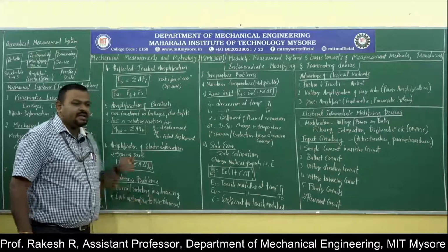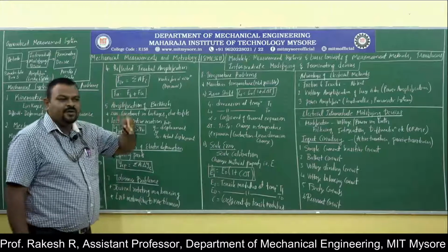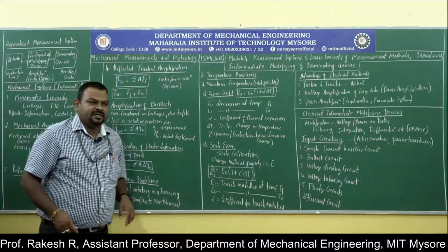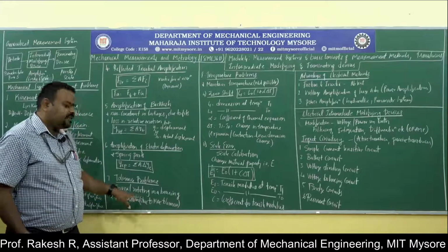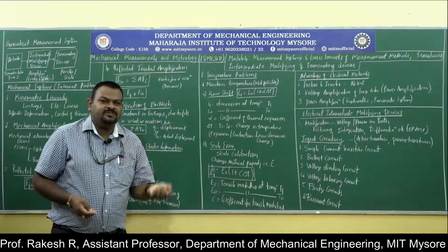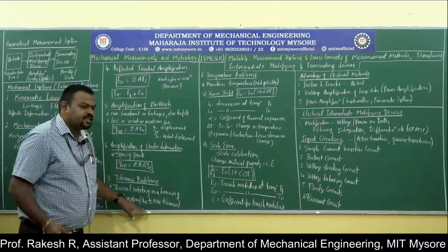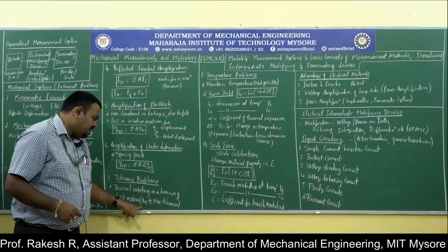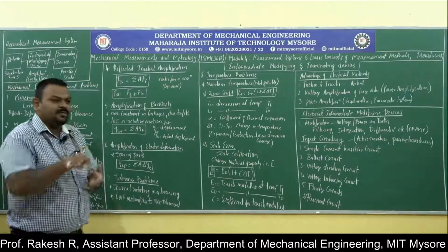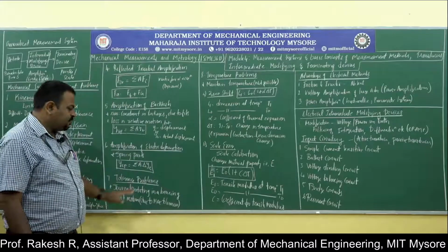Here we are giving a clearance fit for the journal bearing, and sometimes, whenever you apply load, the axis should not be changed. That is also the case. Sometimes a journal bearing will be designed in such a way that it can have a clearance fit, or sometimes a transition fit. In most cases a journal bearing will have a clearance fit, and whenever you give more tolerance, the motion will be lost. There will be offset error, and because of that the movement will be lost.